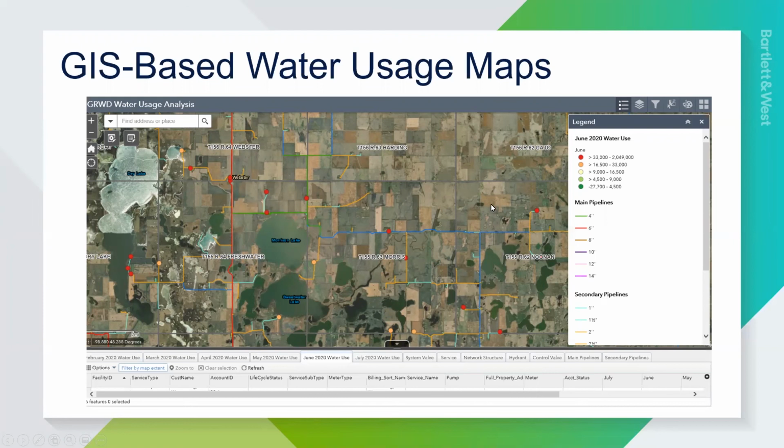And what we ended up seeing happening in this area is all these customers, all 8 of them, were pulling water at the same time due to spraying. And that creates a scenario that acts a lot like an open pipe. Everybody opens their tap and takes the water they will get. The pressure, especially for the guys that are further off the main, is going to fluctuate greatly.